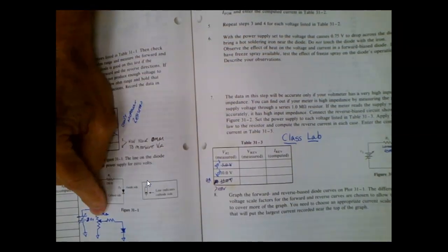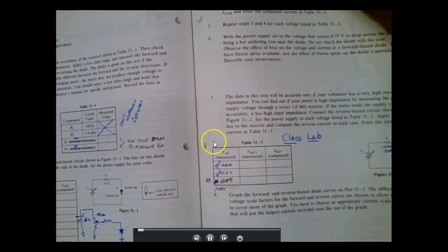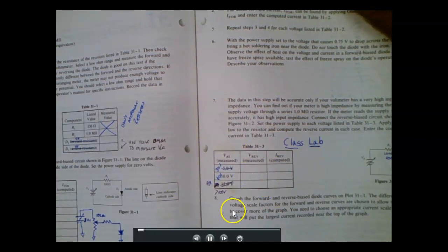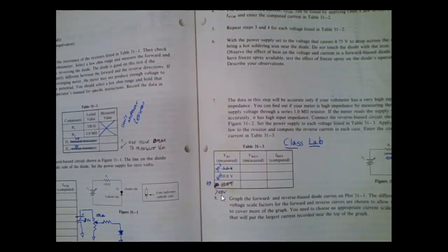So this is the lab. This is the actual modified circuit. These are the 10K pots right here that we'll be using. And we're going to do this as a class. We're not going to do this individually, like I said, because we've got to get up above 100 volts to cause this thing to break over. That's lethal. So that's why I've got all these power supplies stacked up here.